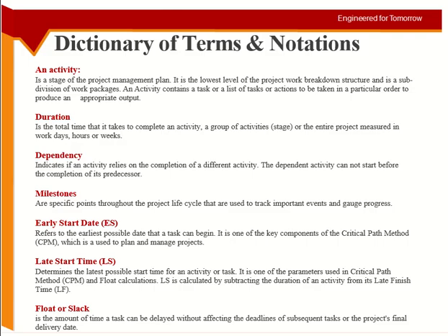As I told you, and showed you in the example as well, when I shift the activities between early and late time, the project duration remains the same. So float is that amount of time where you can shift an activity without affecting the project duration. So there is a difference between early and late start basically.